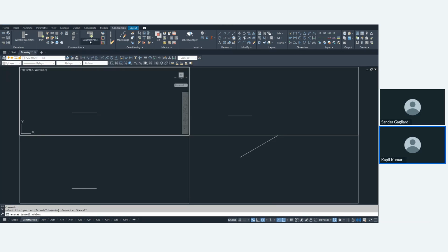Generates panel, we are doing only this command, align and dimension material. Suppose you create a top panel with grain direction lengthwise, but later the client told you we don't require grain direction in length direction, we want grain direction in widthwise. So you can change the grain direction accordingly, then your cutting list will automatically update as per your grain direction.